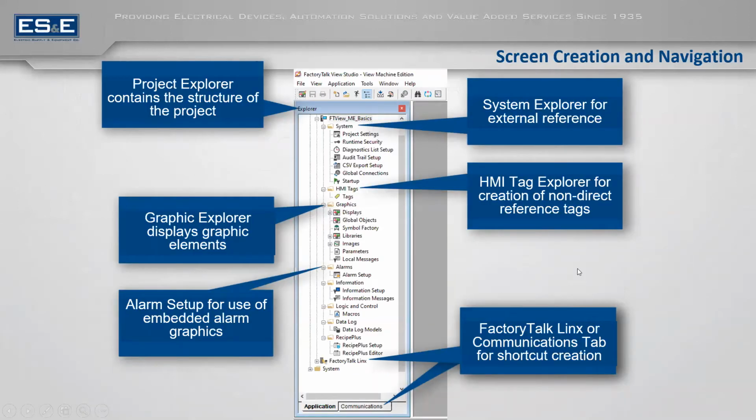So once you create a project, it will open up and it'll look just like the screenshot that I have here. So you have your Project Explorer, which has everything, which is very, very similar, right, to the Studio 5000. Inside there, though, you have a couple of key areas that we always try to focus on. You have your system folder. Your system folder really has all your external setup and configuration. So it'll have security for the runtime. If you do need to change the panel view, it would be set in the project settings of the system because you're changing the hardware.